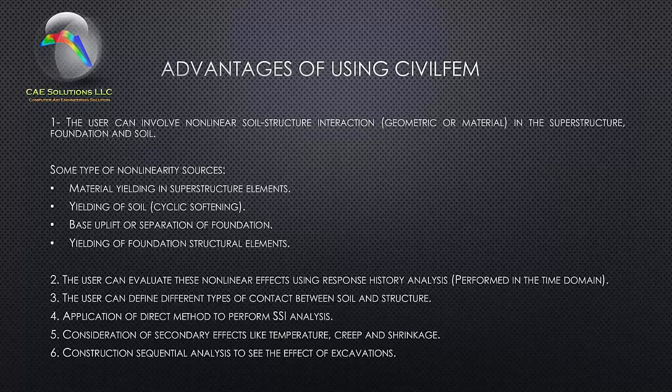Some types of nonlinearity sources would be material yielding in the superstructure itself, its elements. The yielding of the soil, say softening for instance. Base uplift or separation of foundation. This is a nonlinear effect. Yielding of foundation structure elements. The user can evaluate these nonlinear effects using response history analysis, which is performed in the time domain.